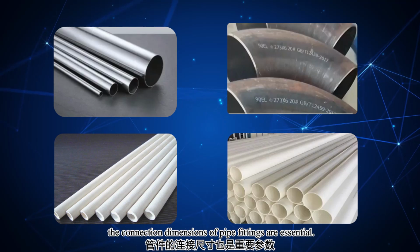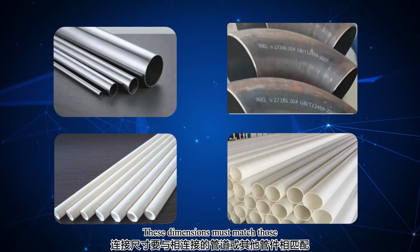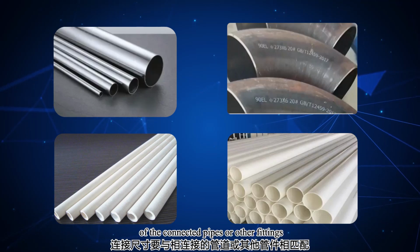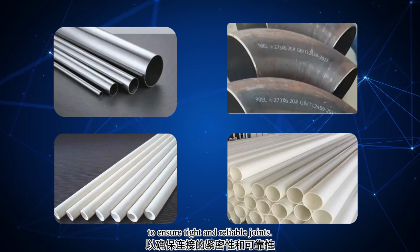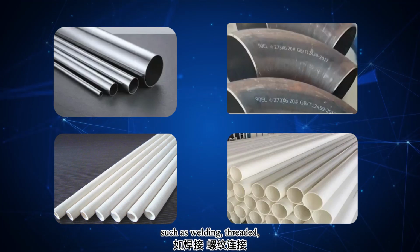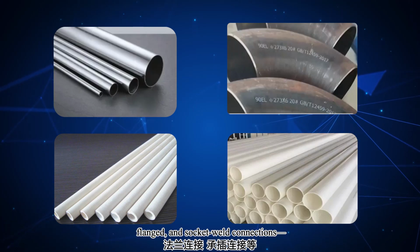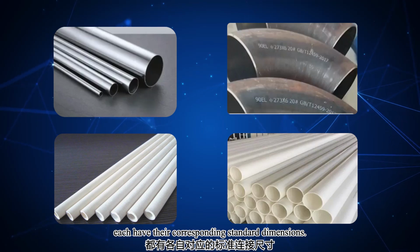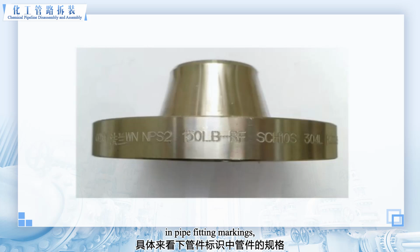Additionally, the connection dimensions of pipe fittings are essential. These dimensions must match those of the connected pipes or other fittings to ensure tight and reliable joints. Different connection methods such as welding, threaded, flanged, and socket weld connections each have their corresponding standard dimensions. Now, let's examine the specifications and parameter meanings in pipe fitting markings, using flanges and elbows as examples.